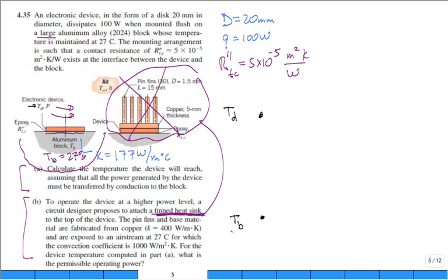But what offers resistance to heat transfer? There's two things that offer resistance to heat transfer. One is getting it through that epoxy. True? Isn't it getting it through the epoxy? So that resistance is equal to R double prime TC divided by area. And if I do it right and I look at the units, won't this give me how many degrees C temperature drop will be there across that resistor per watt of flow?